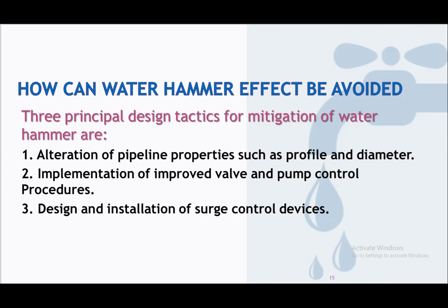And the third point, and this is a really important point, design surge control devices. This will be if you have, let's say, a system for supplying water, okay? In normal conditions, we won't have any problems. We won't have a water hammer problem. But as I said, water hammer happens at emergency cases, okay?